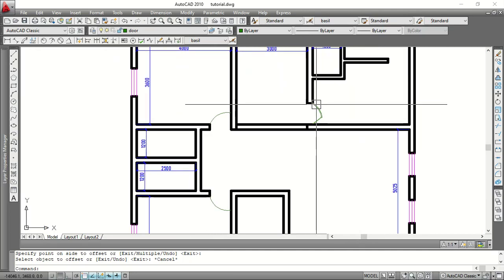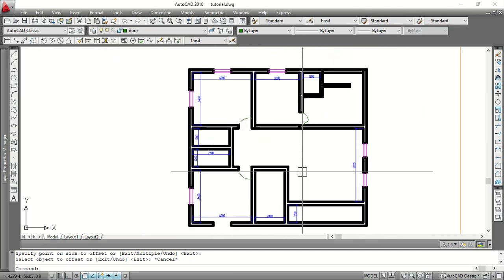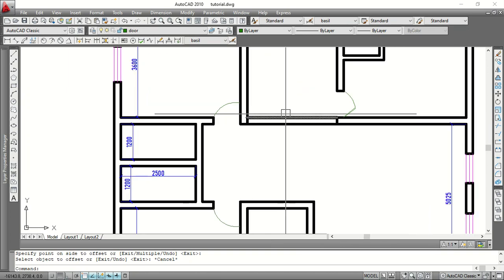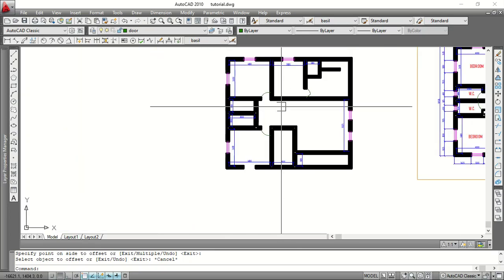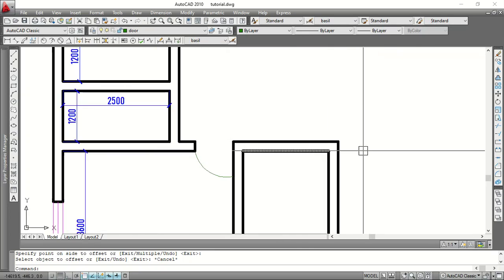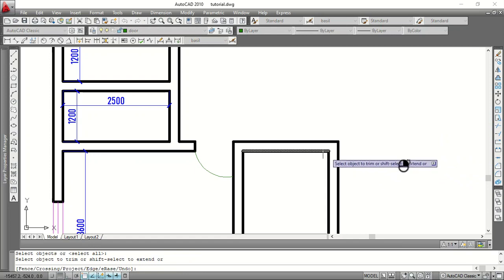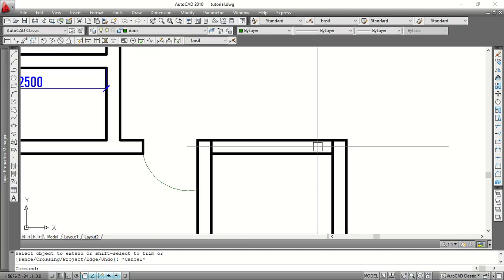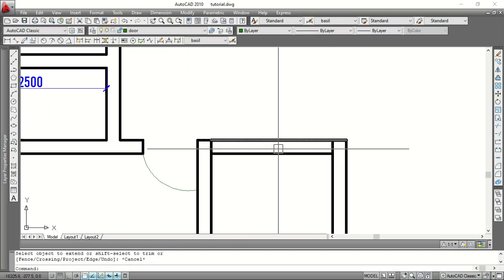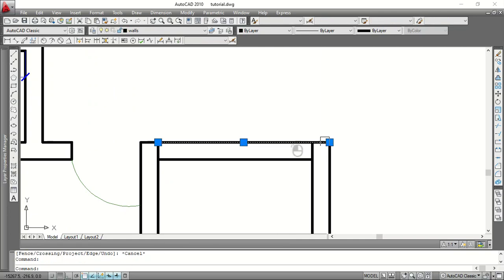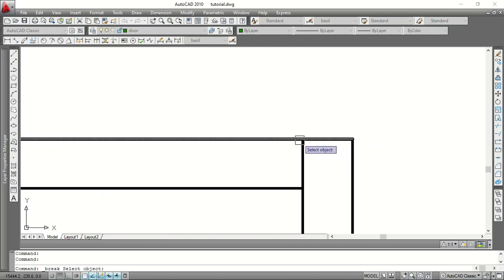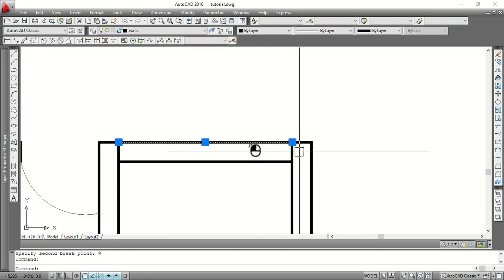All right, so I haven't done the door. Let's do a quick one. The opening, you could see there is an opening here. There's an opening here, and it's an arc. Same thing is going to happen to my staircase area. So first of all, I'm going to extend these lines, extend these, and extend this. Okay. Then don't forget what we did the other time. This line is extending all the way through, and I don't want it that way. So I'm going to break it at this point so that this guy can be on his own.